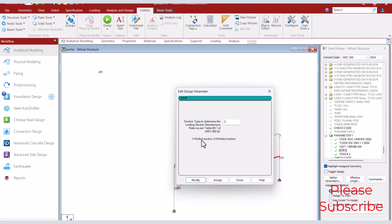to be treated as a roll section or the welded section. If you don't provide any value, it would be treated as an STP value of 1, which corresponds to the roll section. What would the program do? It will select all the cases meant for the roll section while undergoing the section classification, as well as all the different design clauses meant for the roll sections.